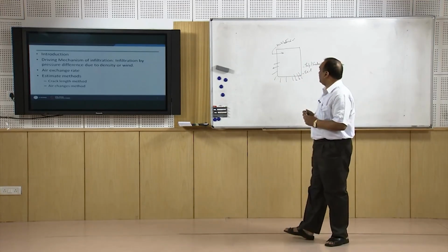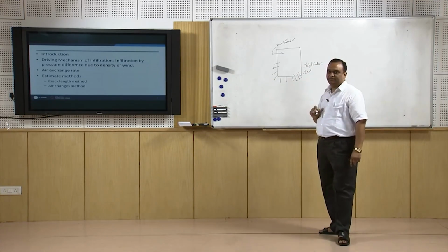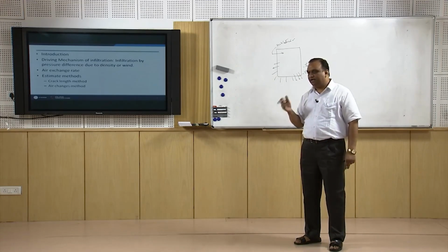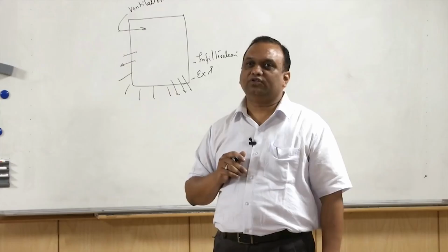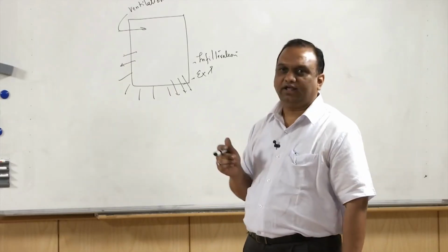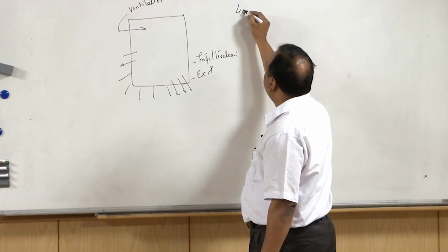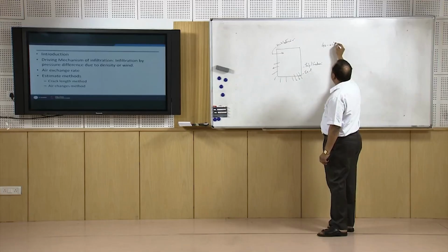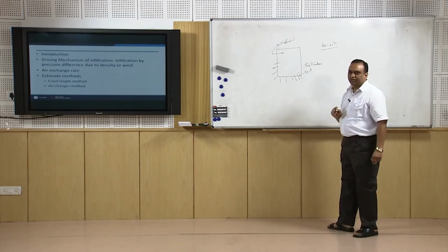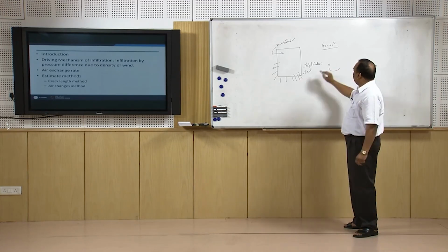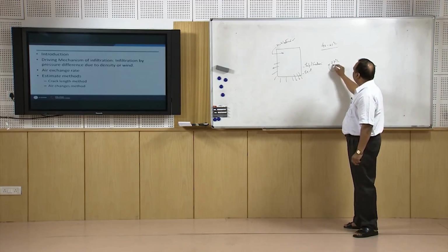If we reduce this amount of fresh air, this ventilation air, then definitely the load on the cooling coil will reduce, because outside air, which is fresh air, in summer, let us say, is available at 40 to 45 degrees centigrade. Instead of using this air, if I use return air which is coming from the room, it is at 27 degrees centigrade.